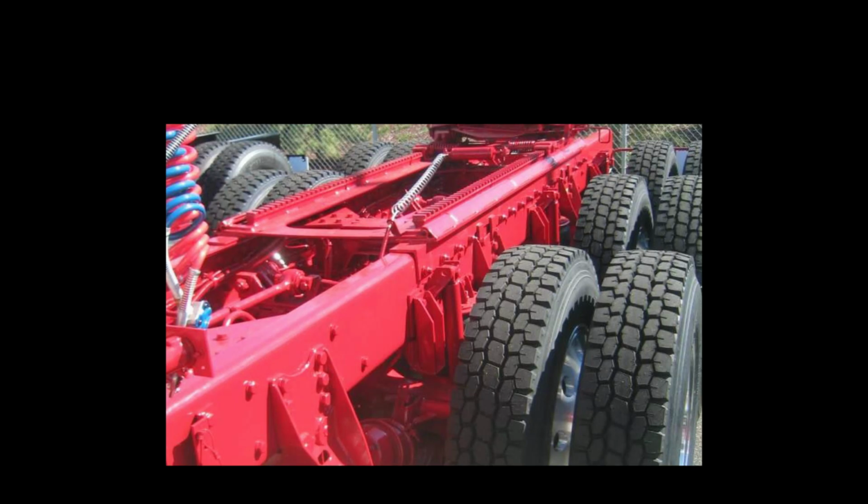The weight of a frame rail is calculated in pounds per inch for the rail pair. Adding inserts increases the tare weight, which reduces payload capacity. Overspecifying rail material can lead to unnecessary weight and decreased efficiency. Most sales tools cannot perform a full frame strength analysis, so collaboration with engineering is essential. They will identify underspecified chassis and provide solutions.